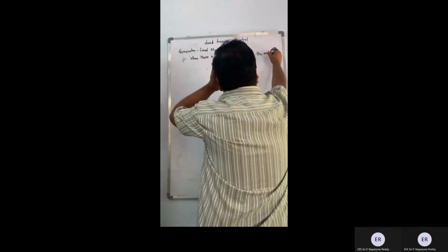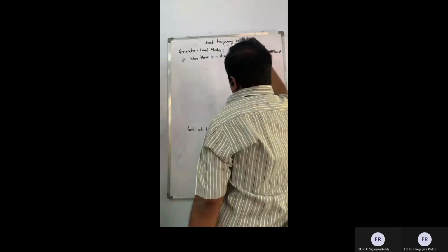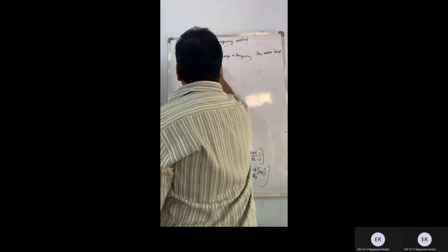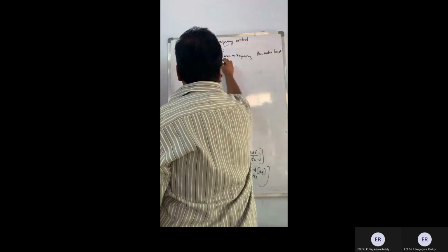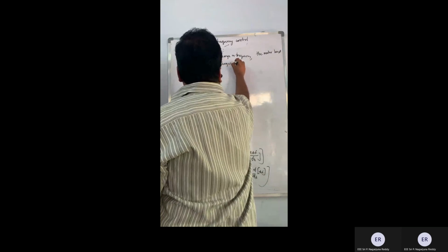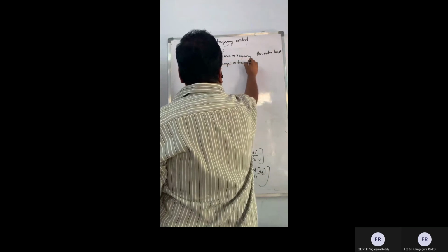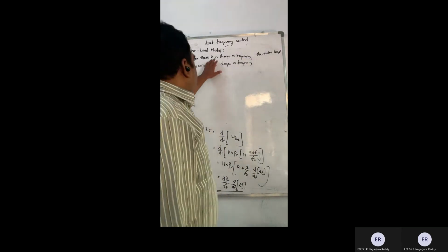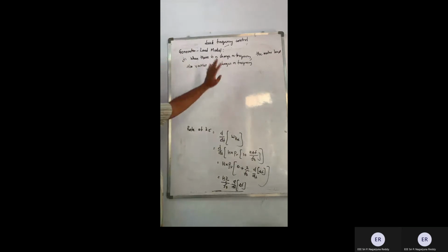The motor load also varies with changes in frequency. Why? Because the load is normally sensitive to the frequency, even though the sensitivity is very, very low. But we'll consider this one also. So when there is a change in frequency, then automatically the motor load is also going to vary.